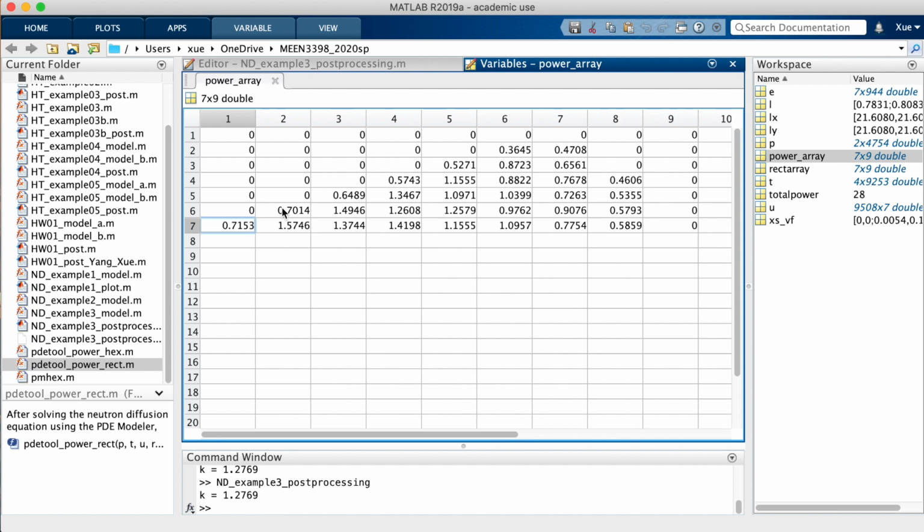So when we perform the numerical integration, we only get 1/2 of the power. However, in the real reactor, those assemblies are going to produce twice the amount of this value. Therefore, we need to manually double those values.